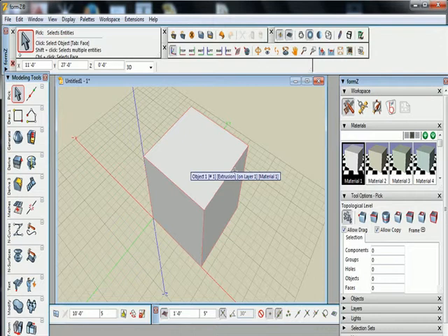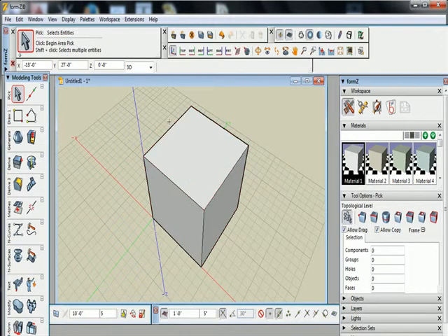If we measure this, it'll be like 12 feet over in this direction and 9 feet over in this direction. Okay, so we're going to draw a guideline, and the guideline tool is this guy right here, right next to the pick button.